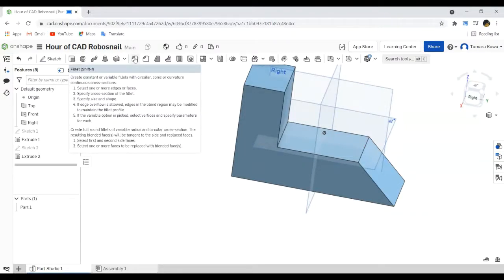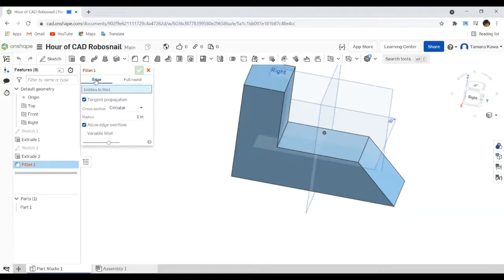All right. Thanks, Aiden. So we're going to click on fillet. Again, all these words are going to show up if you're hovering over the right button. Mainly look for the words fillet or Shift F or something. So you'll click there, and you're going to be on edge mode. You'll want to click on whichever edge you want to fillet. Let's start with these guys in here.